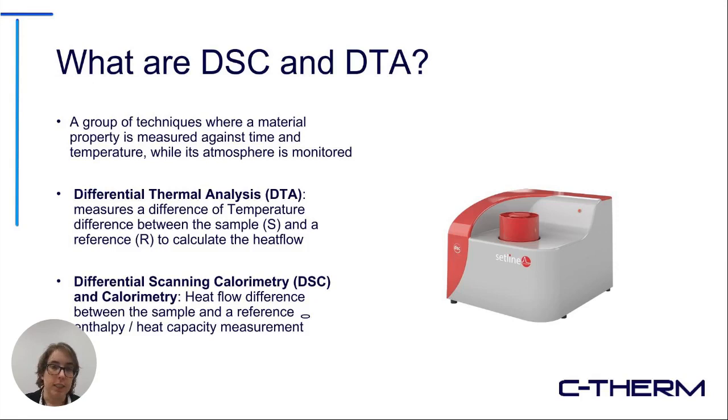The other technique we had mentioned is differential scanning calorimetry. Generally speaking, the primary technique used nowadays is the DSC technique, or differential scanning calorimetry, but there is a bit of an older technique called differential thermal analysis, and that's still used sometimes in some more challenging applications, where a cheaper, more easily replaceable sensor is sometimes attractive, or in cases where you really need to be super responsive to the onset of a thermal event, where the lower thermal mass of the DTA sensor can be useful in helping to resolve